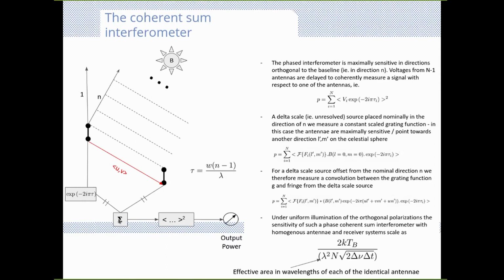So we're adding coherently the signals, the induced voltages between these two antennas, and we can scale it, of course, to any number of antennas. We then square that integrated voltage, and out comes some power, exactly as we had with a radiometer earlier on. So if we express this in terms of mathematics, we get a power out from n coherently summed antennas. Why is it coherent?